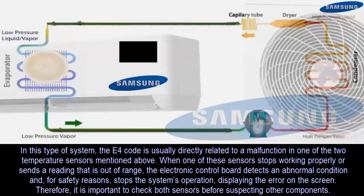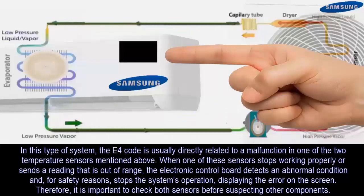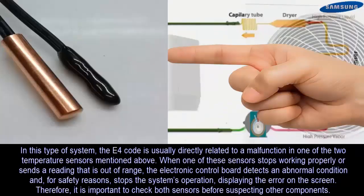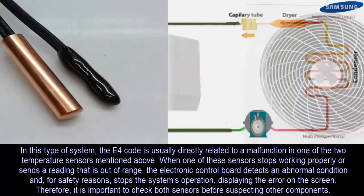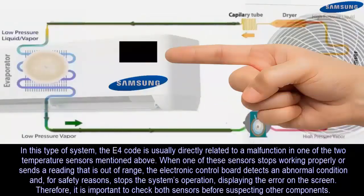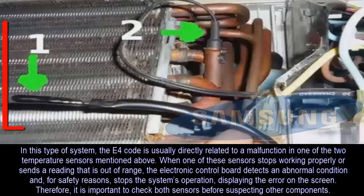In this type of equipment, the E4 code is usually directly related to a failure in one of the two temperature sensors mentioned above. When one of these sensors stops working correctly or sends an out-of-range reading, the electronic control board detects an abnormal condition and, for safety reasons, stops the unit's operation while displaying the error on the screen. That is why it is important to check both sensors before suspecting other components.